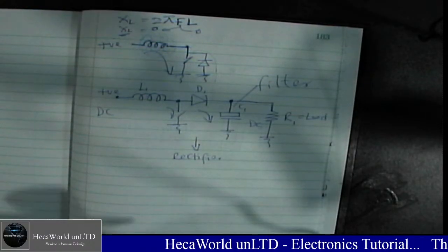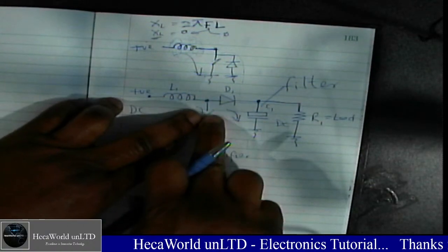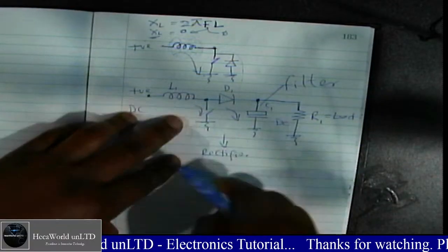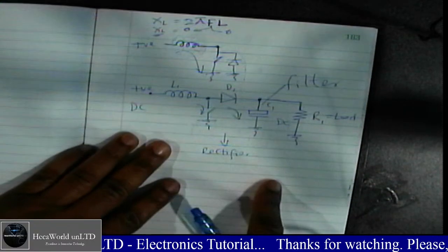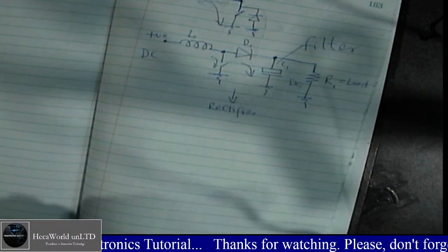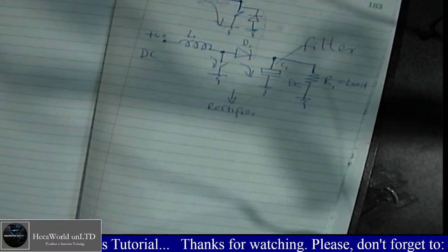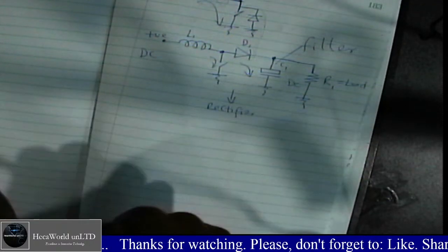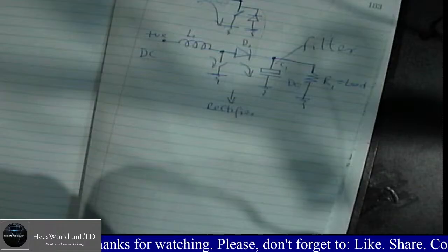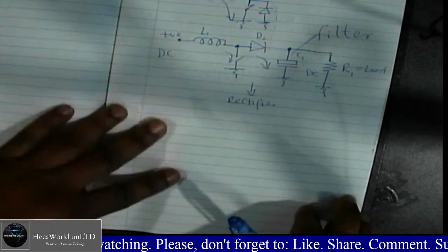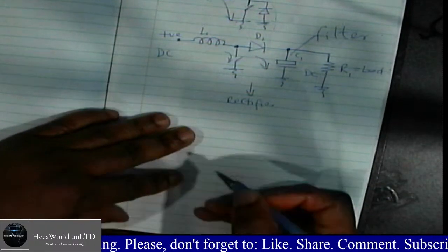Now, you need this to be switched at a very high frequency. So you're not going to put your hand in your circuit and be switching it up, down, on, off, on, off. No, you're not going to do that. So here is where we're going to use other components to act as a switch. Now, we've worked on something we called a transistor switch before. So we're going to use a similar thing right now to create the DC to DC converter.